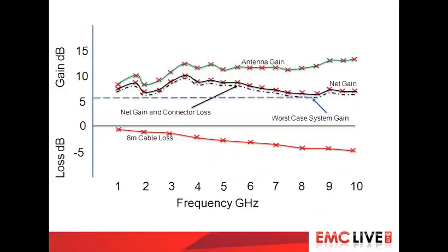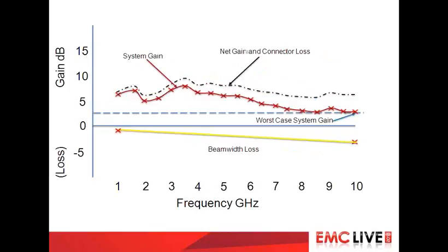So what do we have? We have a situation whereby, starting with your antenna gain across the band of interest that we're designing, and factoring in one by one the different losses, in particular, as I've introduced now, I don't think I've seen other people do that regarding beamwidth as a loss. Putting that in as a loss too, you can get an overall gain. Well, there we go. We get an overall gain, and we can get that system-wide gain, plug that into the power required equation, and come up with the actual power that we need.